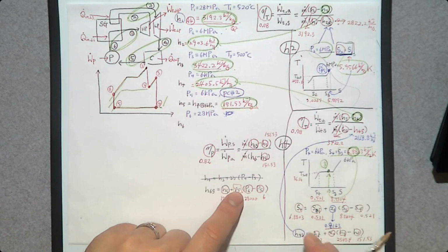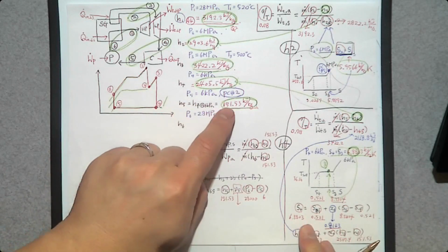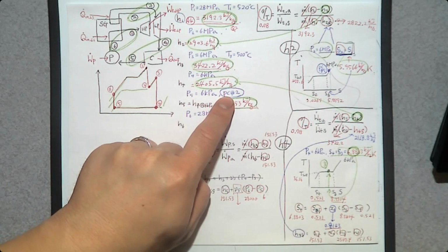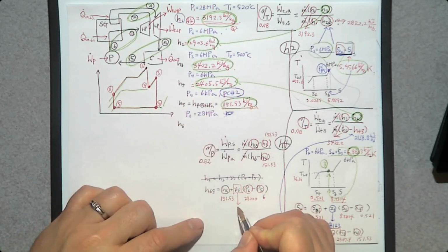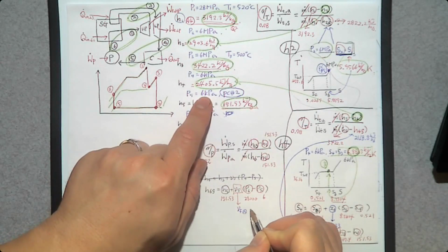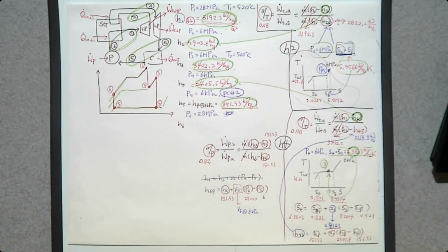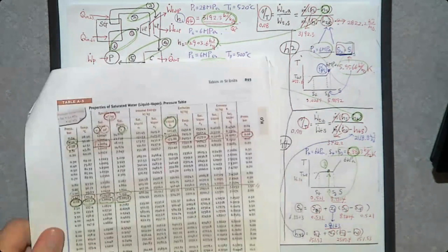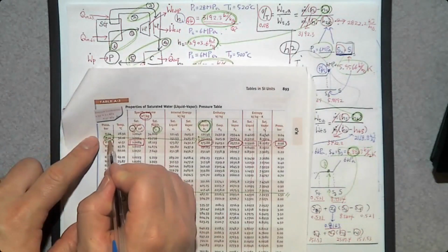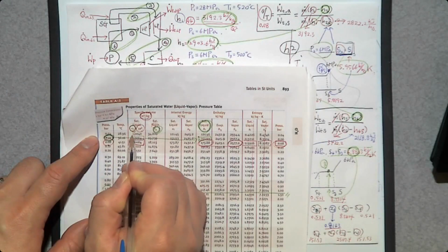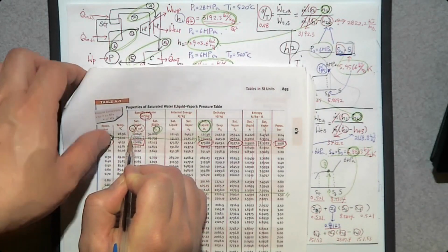How can we find V5? Number 5, we have phase change process number 2, saturated liquid. So V5 is going to be Vf at what condition? 6 kilopascal. Can you find Vf at 6 kilopascal? Yes, if we go to the table, 0.06 bar, which is 6 kilopascal, Vf is going to be 1.0064.